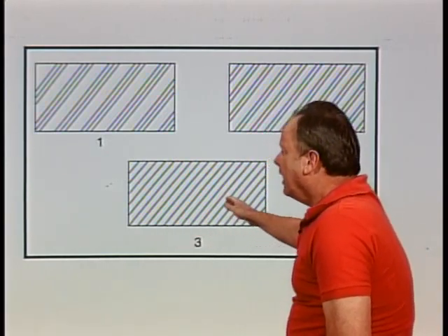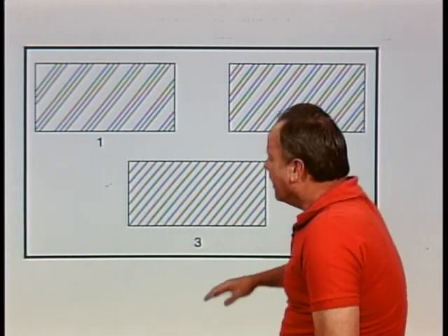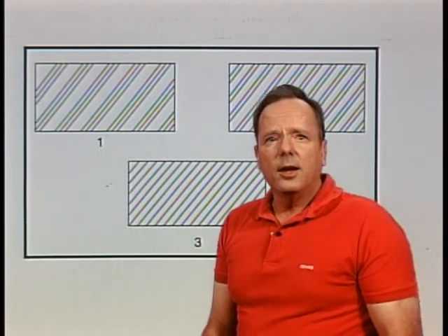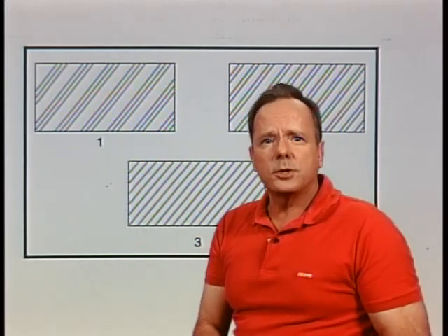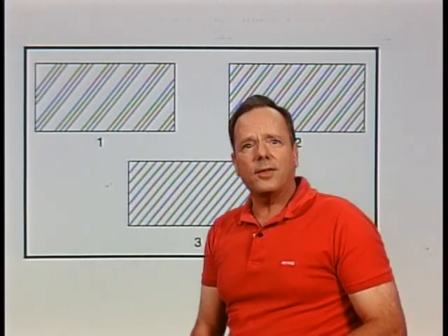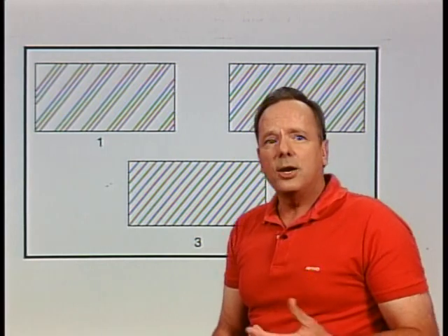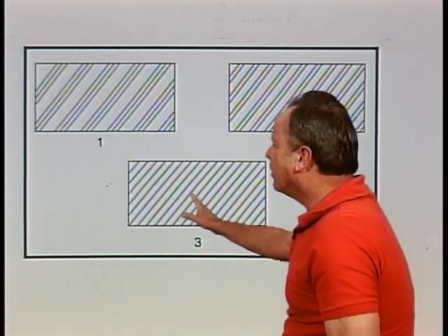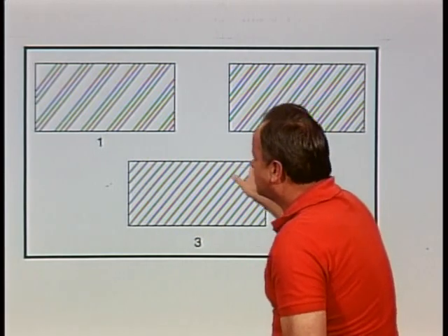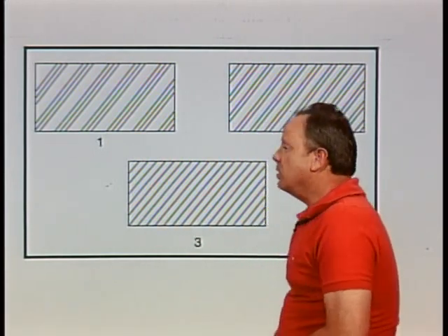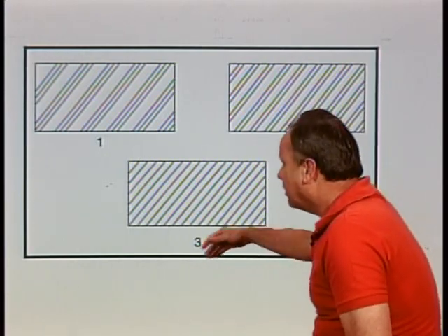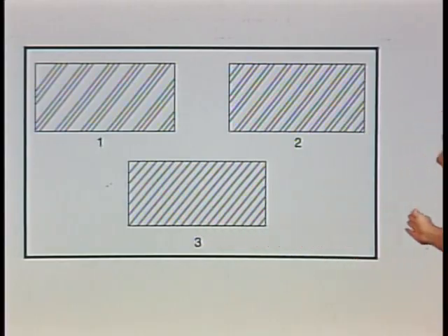It's number 3. And if you are making a drawing, for instance, a working drawing for an individual part, normally the kind of material that would be used is going to be specified on a note somewhere or on a parts list. So therefore, it's not necessary to repeat the information by using a specific section line symbol. And if you just want to use a symbol that says, look elsewhere for the material, this is just showing you that there is material, what you do is use a symbol for cast iron.